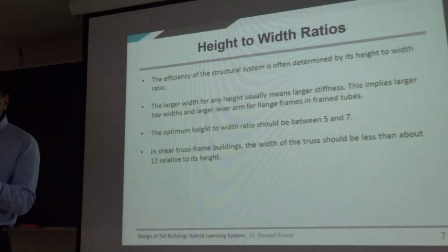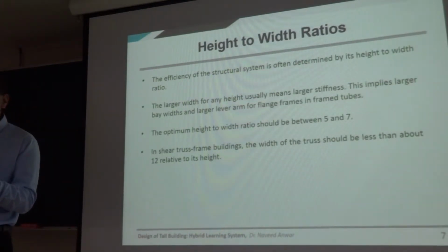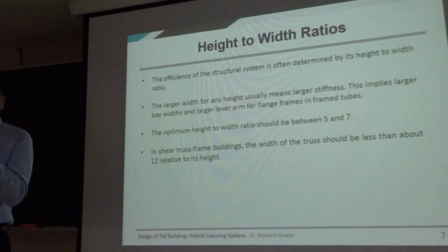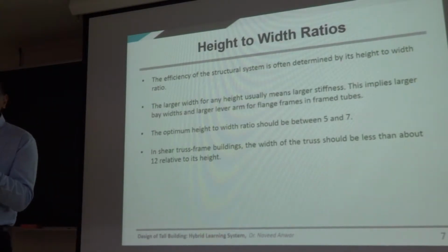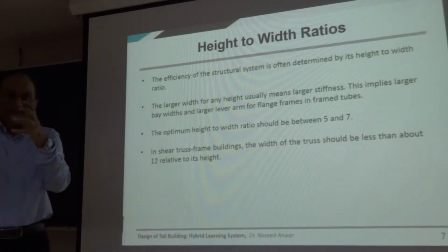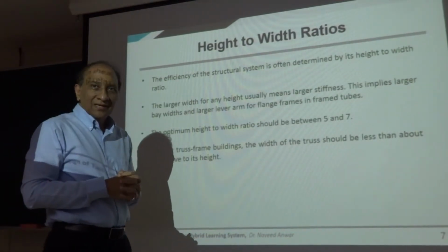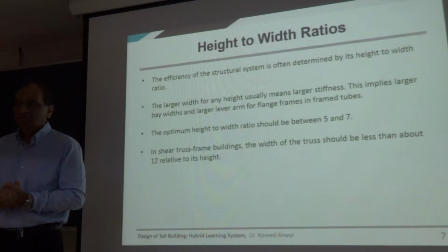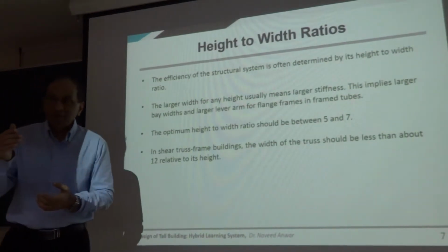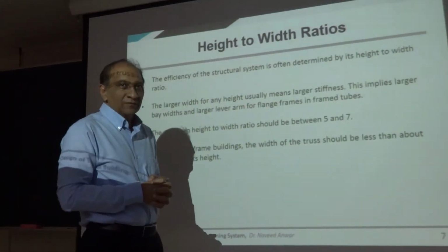After 10 floors, the load is reduced, so you need another size. Another 10 floors, the load keeps reducing, and you can theoretically keep changing the column size as you go up, right? That will be the optimum design from the point of view of the calculation.